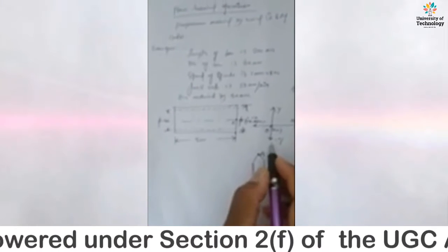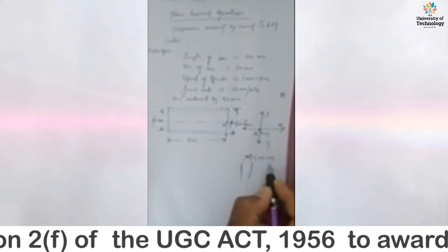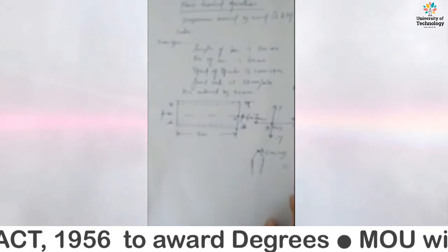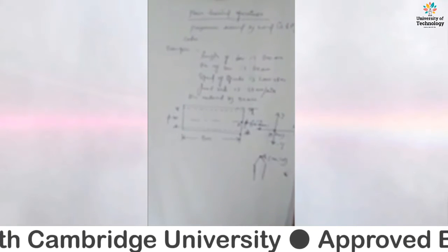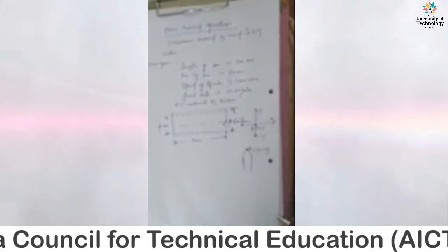Pre-position of the tool, we can define any positive coordinate like 20, 20, because the machine is at rest on the home position, and the home position coordinate is not known, so we first take the pre-position of the tool at point 20, 20.